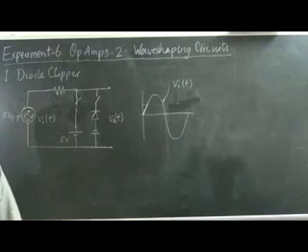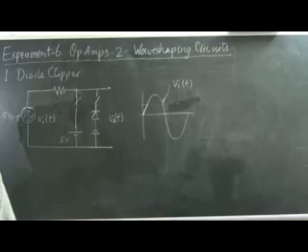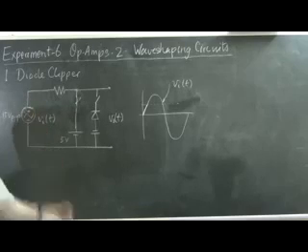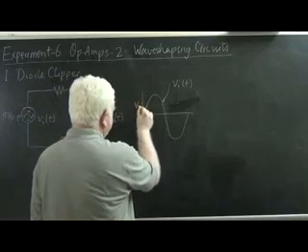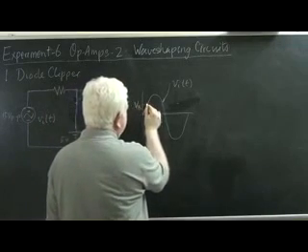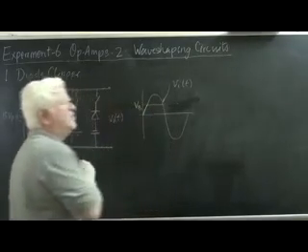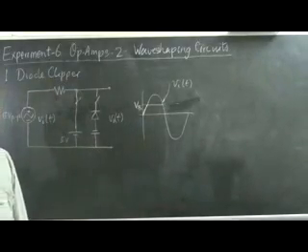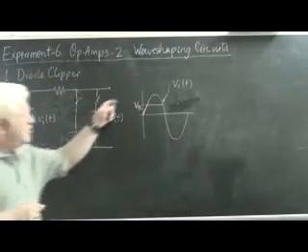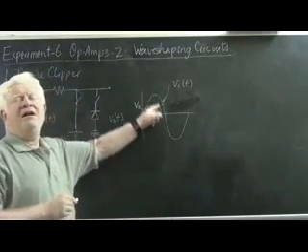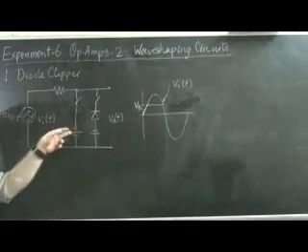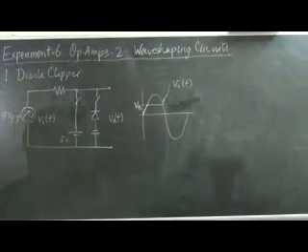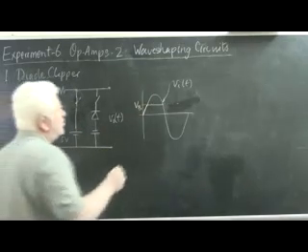So let's ignore 0.7 in our discussion because it's obviously going to be there, and say it levels off at VB. So this is VB, and at this point the output remains at that level. However, when the input curve starts falling and lowers itself to below VB, again this diode becomes open as we showed you earlier, and the output voltage mirrors the input voltage, reflects the input voltage.